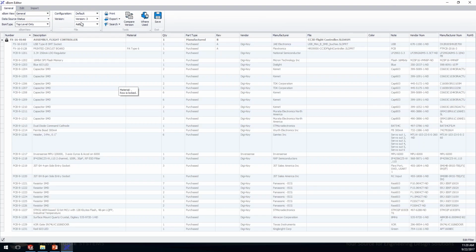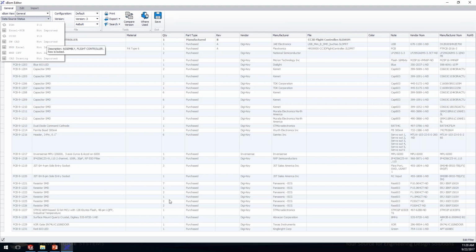So this allows you to version control and manage these components and these bills of materials independent of what you're doing in SOLIDWORKS, but still linked, so that if the SOLIDWORKS assemblies change, the source materials change, maybe the Excel BOM here changes because you had to swap out some components. Right. You can always come right back to here with it checked out and refresh. You'll see if the versions are out of date, and you can make sure that the combined BOM is always up to date.